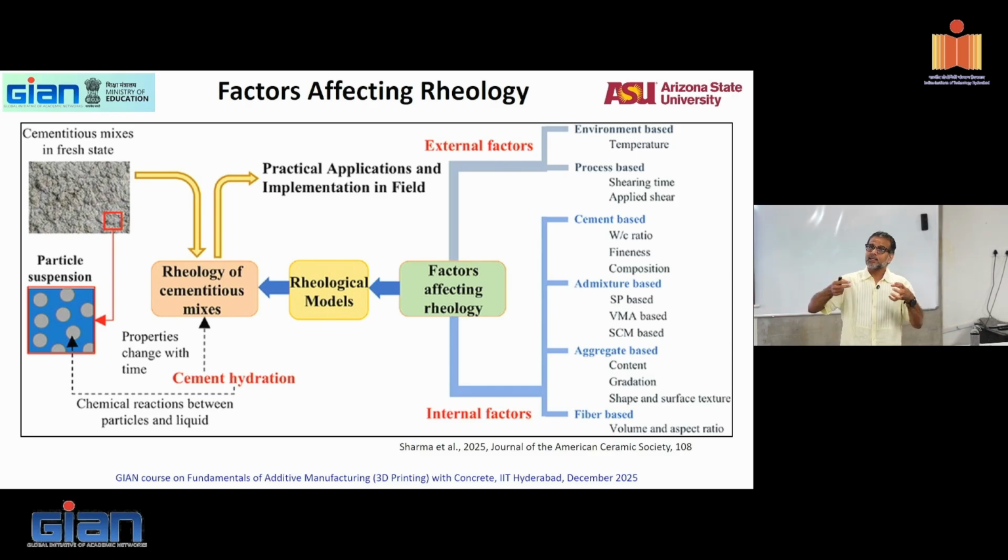So how particles pack in a given volume will tell you how much water is available for it to move in between the particles to shear and move the particles, which will affect the workability, which means particle size and particle shape are very influential. Because we cannot control particle size and particle shape, we happily go to an admixture guy and say, give me your magic chemical, let me add it and get my rheology correct. You can do admixtures.